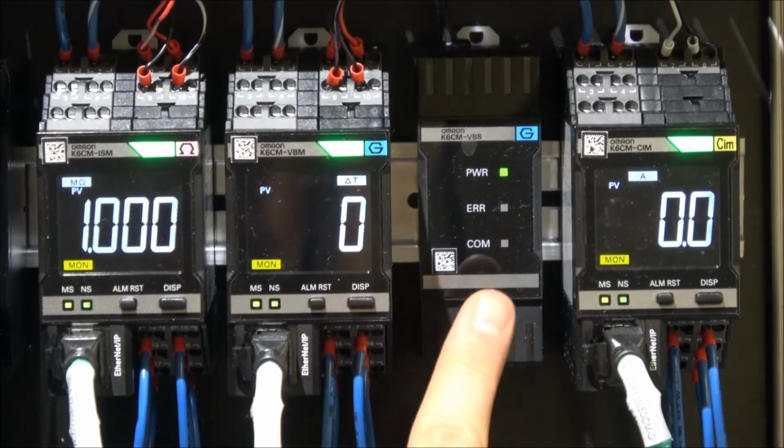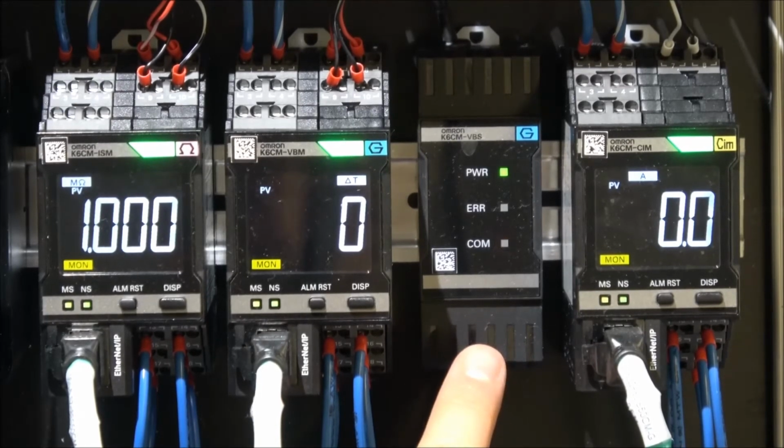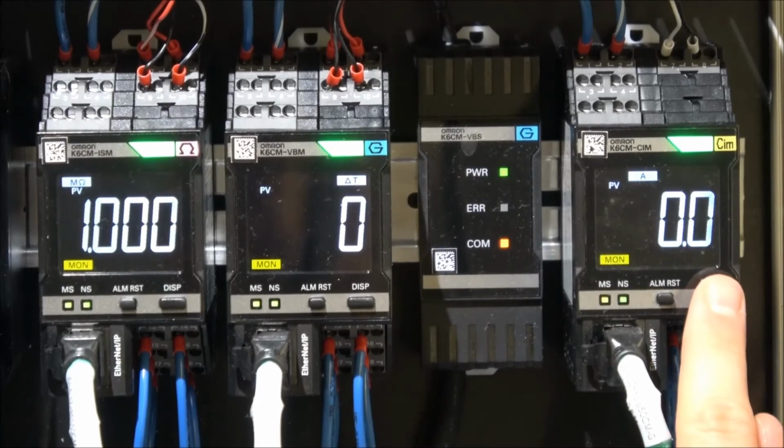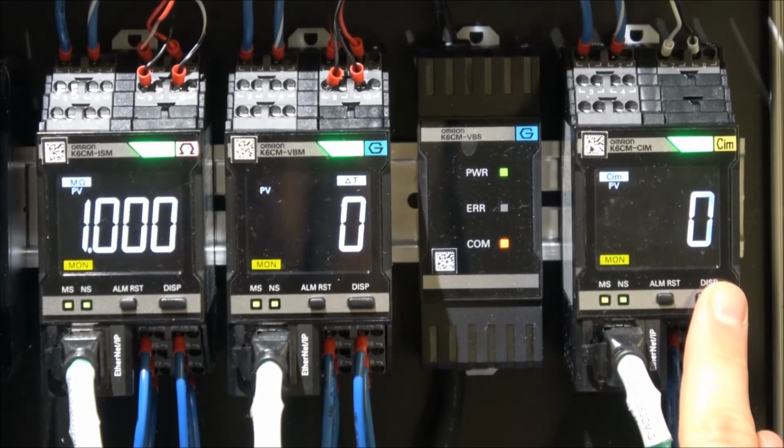ambient. Right here is our vibration amplifier, which is also measuring the ambient temperature to compare to in the delta T. And lastly, the current analysis will show the current as well as the degradation level, the deviation from a uniform sine wave that will result in some kind of warning or critical threshold.